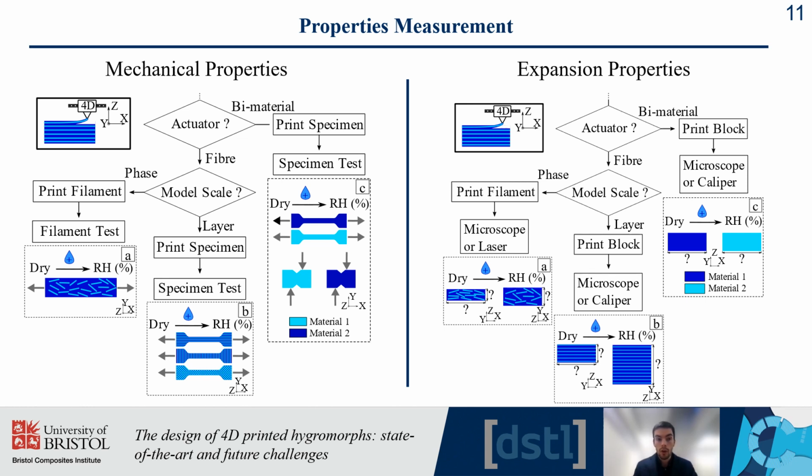For instance, I use coefficient of moisture expansion, others use hygroscopic strain, others use volume changes. They all mean the same thing, but knowing which would be the most efficient in order to account for this deformation capability would be an efficient way of comparing different materials and predicting the deformation of the structure.